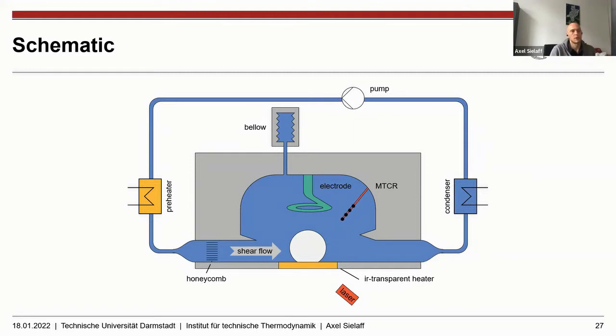From a measurement point of view, we have a device, which you have seen in the first video, which could be brought down to the heated surface or back to the home position. So unfortunately, moving this device failed some time after the beginning of the experiment. So we just got the data from the device in the homing position. And for sure, we could observe the process with an infrared camera, a high-speed infrared camera, and with a black and white camera, not looking under a 55-degree angle, but let's say perpendicular to the slide, so that we can see the bubble shape.